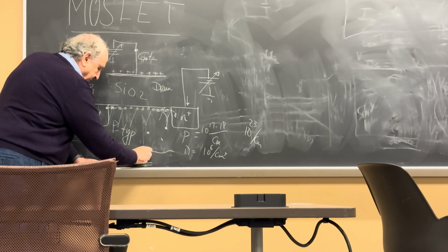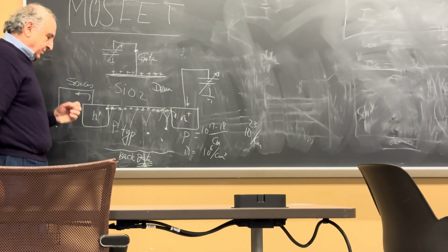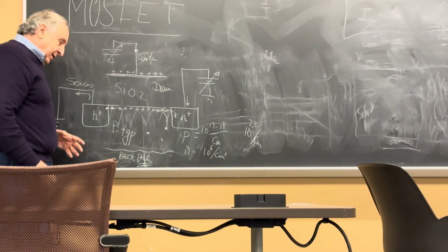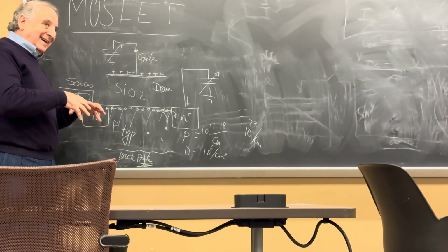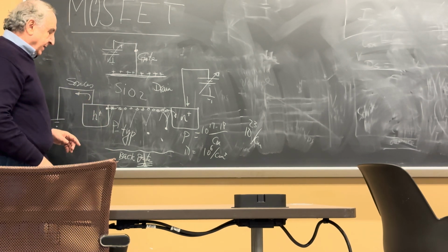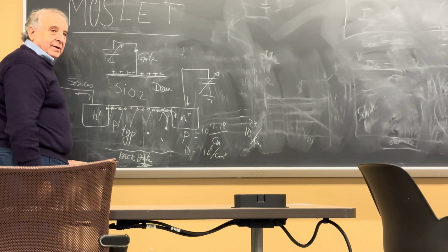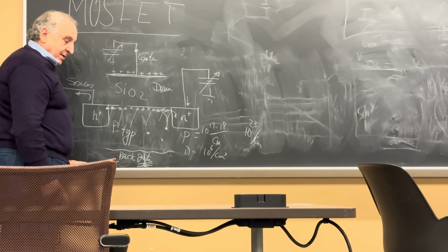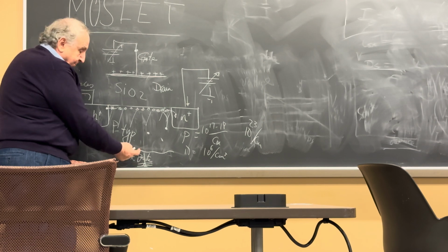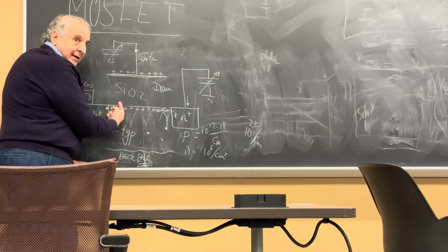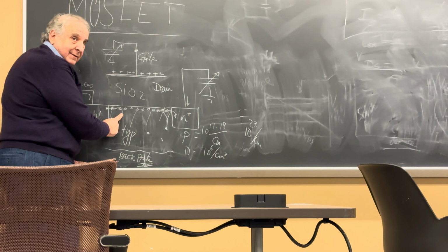Here it is. Let me show you why this is very important, especially in amplifier design, IC design. Does the back gate affect how many electrons are in here? Yes, it does. If I put a positive potential here, I push these electrons further out, right? I could make more accumulation here.